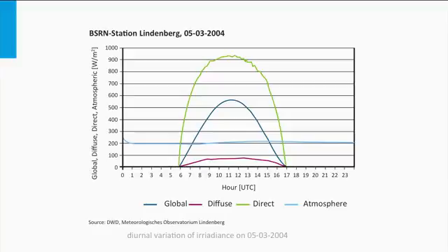In weeks 7 and 8, we will talk about PV systems. You have to realize that the response of a PV system differs between diffuse light and direct light. This week, I would like to show you how we can measure the irradiance of direct light and diffuse light. For that, we use a pyranometer, and you often see these tools installed next to a PV system. These are instruments used to measure the heating power of radiation.